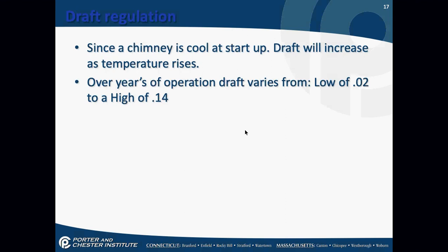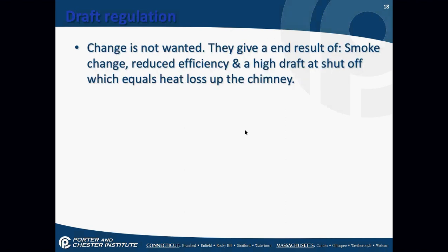A chimney is cool at startup. Draft will increase as the temperature rises. Over a year of operation, the draft can change. It could start off as a low of -0.02, and it could go as high as negative 0.14. The draft will adjust over the course of the year. That's because of temperature differences.